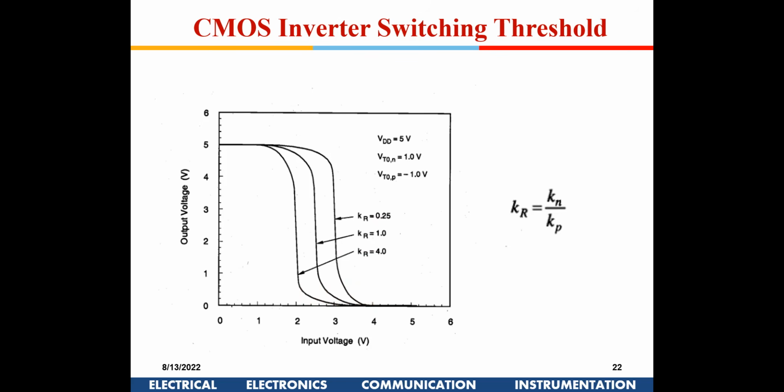Yeah, Gajendra. So you are increasing K. Increasing the? Sir, if you are increasing the KR, that means we are increasing the doping level of the PMOSFET, and therefore the VT of the MOSFET is also increasing, as a result of which the curve is going to the left. No. See, we are talking in terms of a circuit designer.